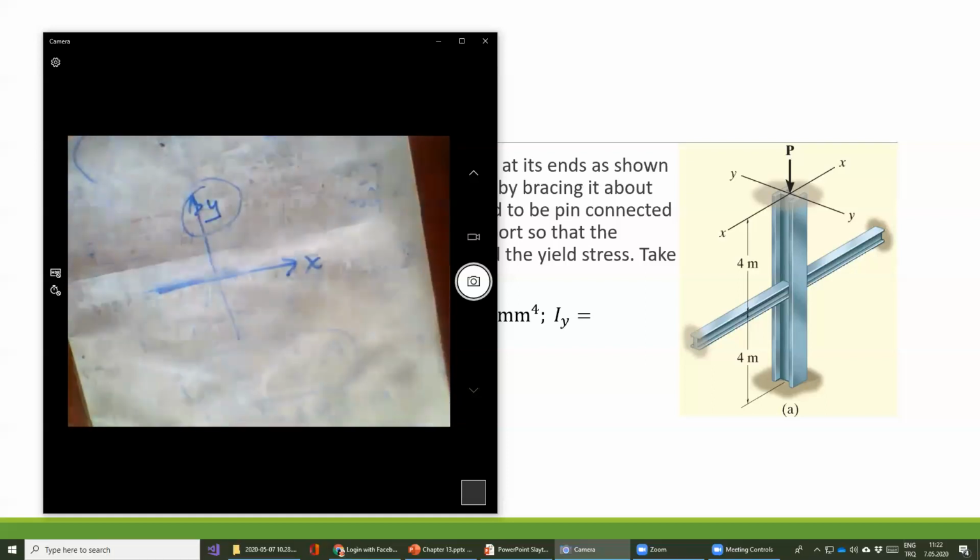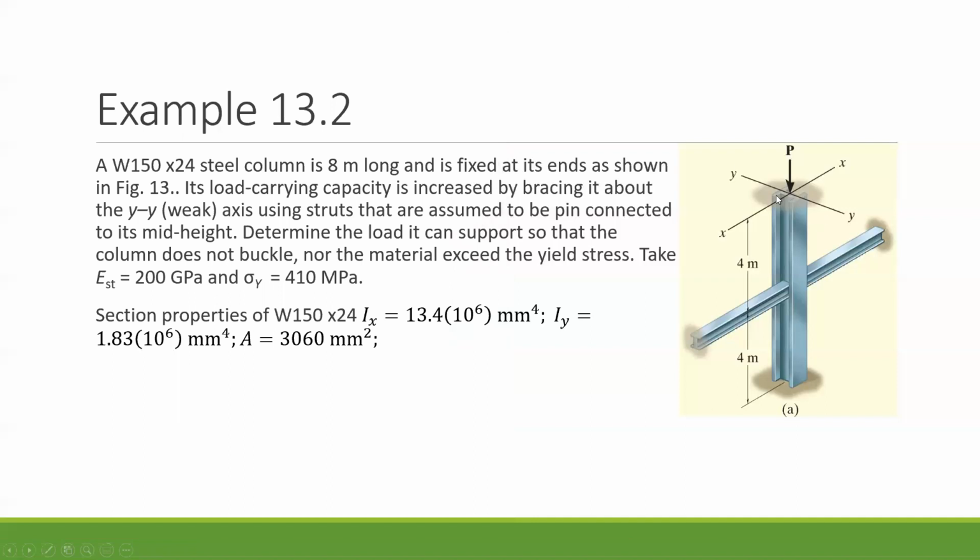Therefore, the braces prevent bending or buckling about the y-axis. Don't forget to use the right-hand rule to determine the bending or buckling side.